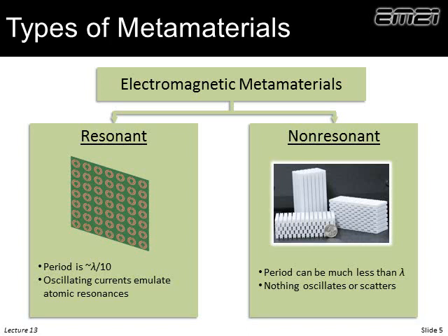of physics takes over. So for these non-resonant type of metamaterials, the cutoff frequency really is where it begins to become resonant. So I'll say 1/10 of a wavelength, although my experience is we can push that a little bit further, but the periodicity can be a millionth or a billionth of a wavelength, and they will work the exact same way. There's no current that's oscillating, there's no waves bouncing around. They derive their properties simply due to where the power is.